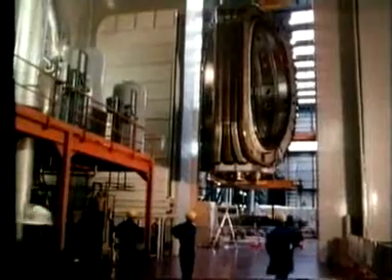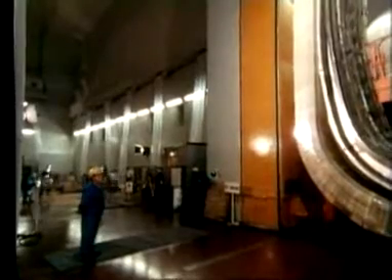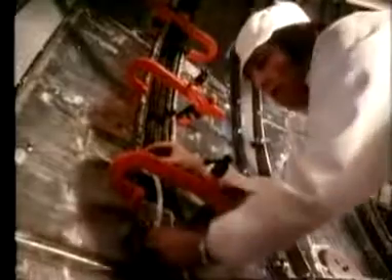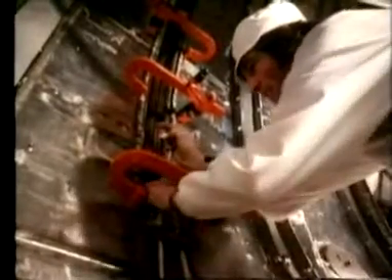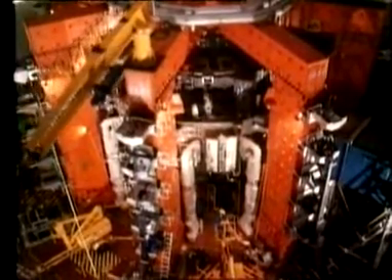The torus hull has concrete walls 2.8 meters thick to shield the operators from the high-speed neutrons. The doors weigh 400 tons each. The neutrons will make surrounding equipment radioactive, so it will need to be dismantled and disposed of. The volume of radioactive waste from a fusion power plant will be similar to a fission plant, but the radioactivity will be far less and will last a shorter time.